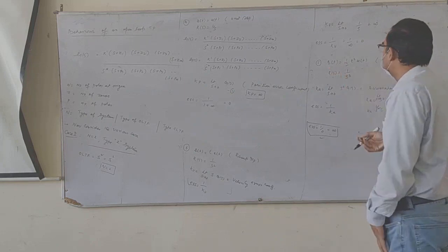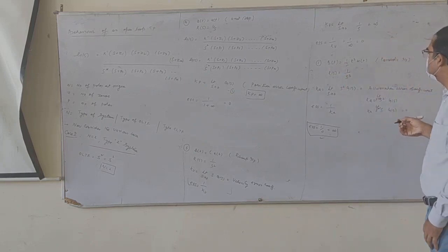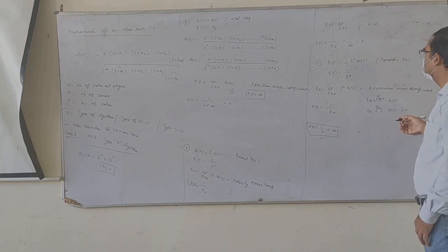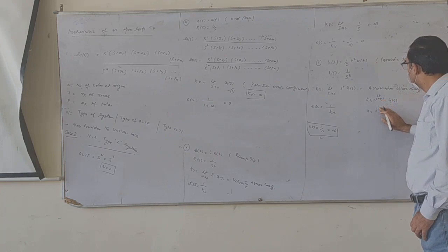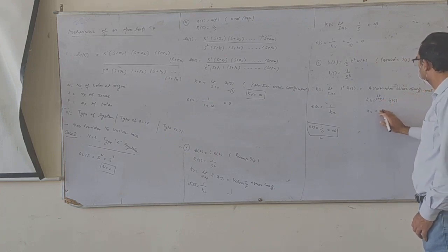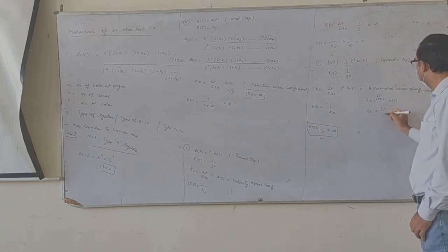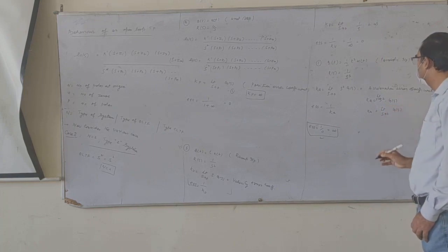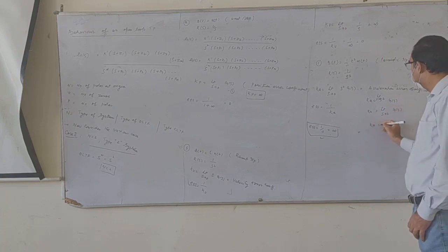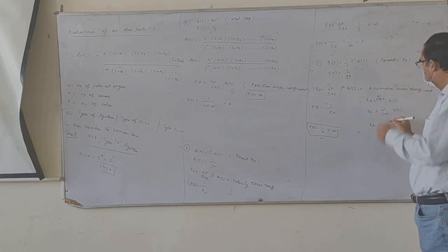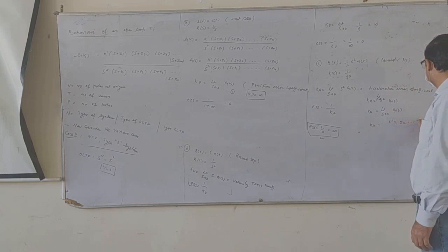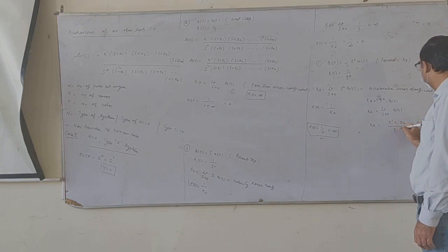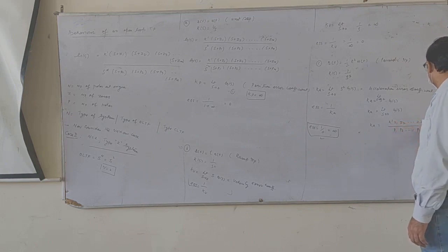Now consider the third case. Same, s square g of s, acceleration coefficient. Okay, s square is going to get cancelled. G of s, limit s tends to 0. Only g of s will be left. So that is what g of s will be. Again the multiplication of all those terms: K dash because s is 0, z1, z2, so on and so forth up to zm, and then this is p1, p2, so on and so forth up to pn.